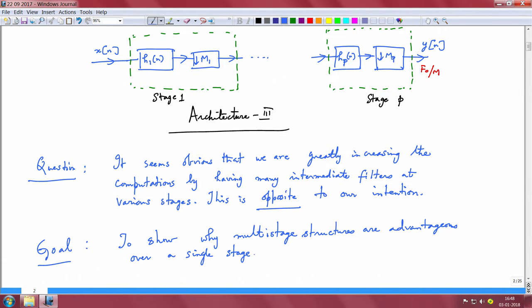But at this stage still you may get a thought in your mind that if I really have a very narrow transition band, the filter order that I would require would be humongous. With a single stage, let us say I am looking at a signal say 10 kilohertz sampled and I want to downsample it by some rate, say 100, and I want a very narrow transition band to accomplish this filtering.